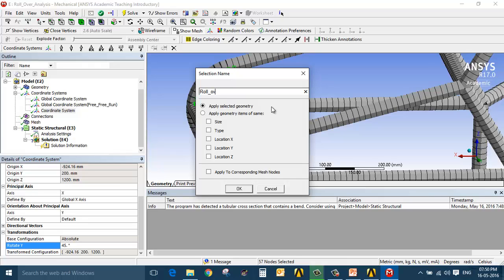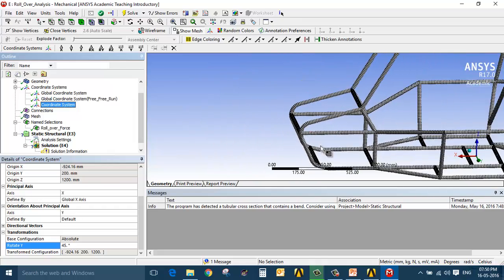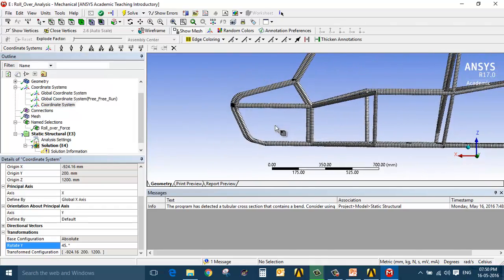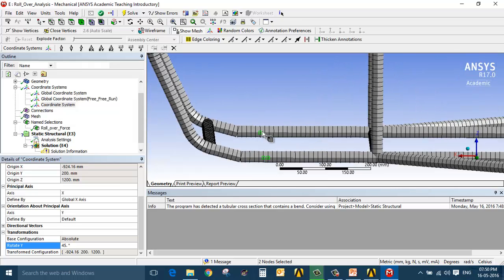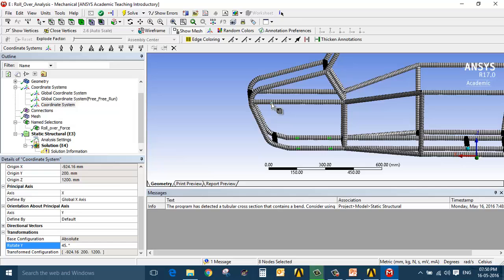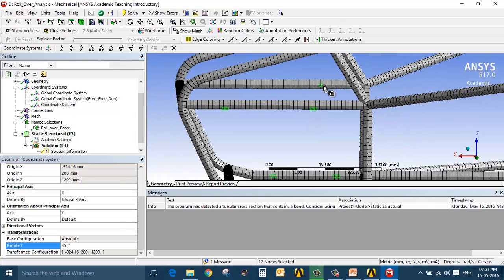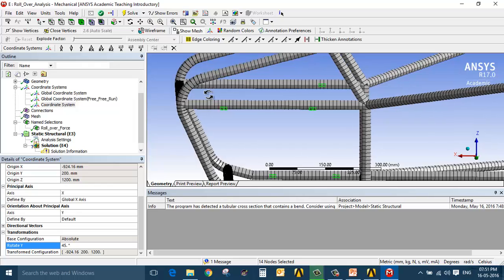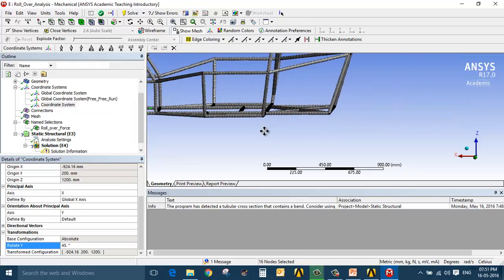And the suspension mounting points. So I will select all the suspension mounting points, these one, these one, these one, these one, to apply the constraints. These one. Oh, I have selected. So again, if you have selected more, you can click there again to deselect them. Press Ctrl and keep selecting the nodes. So click again. Make sure you have pressed the Ctrl button, otherwise you cannot have a multiple selection.